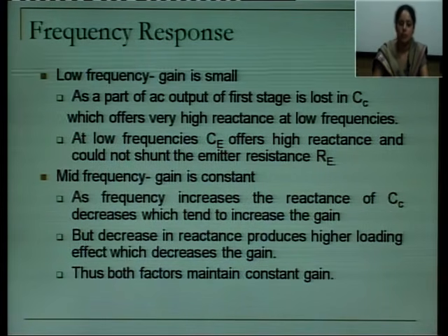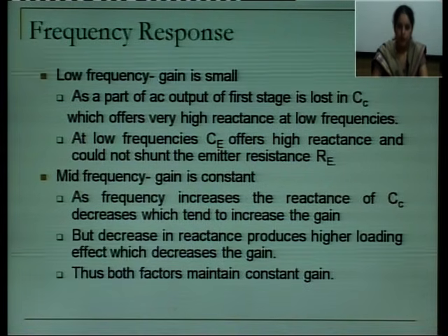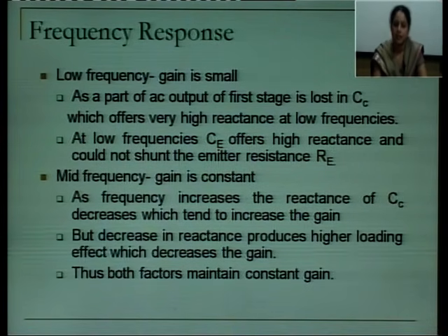So these are two main factors why your gain is small at the low frequency. Now coming to the mid frequency, at the mid frequency gain is constant. Now why is this gain constant? Because we are having two reasons. One provides the increase in your gain and another contradicts it by the decrease in gain. So, the gain that was increased by a level is decreased by the same level, providing a constant gain.